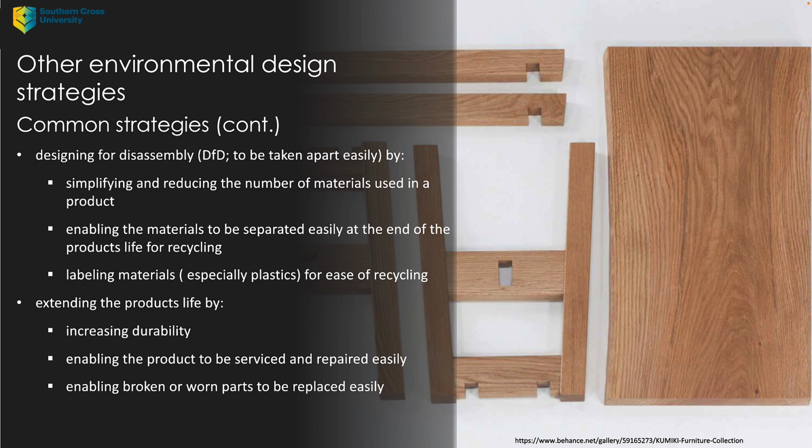Designing for disassembly, DFD, to be taken apart easily by simplifying and reducing the number of materials used in a product, enabling the materials to be separated easily at the end of the product's life for recycling, and labeling materials, and this is especially true for plastics, for ease of recycling. You can see in the background image there, it's an example of a furniture collection, which is actually designed specifically for ease of assembly and disassembly.